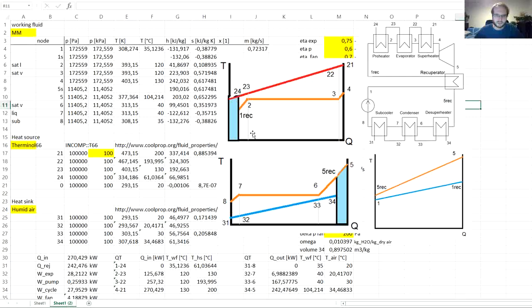source. And similarly, since we get rid of some of the heat already before starting of the condensing heat exchanger, in the superheater part we cut the bit of right side of the QT diagram, so instead of the point 5 the heat rejection will start at the point 5 recuperated, and on the side of the cooling air its outlet temperature will not be that high, but it ends up lower.